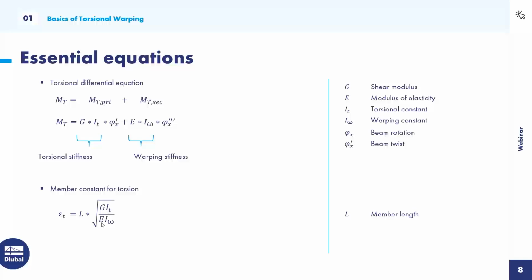And this decay factor has some meaning. The greater the decay factor, the faster the secondary torsional moment is reduced in the vicinity of a warping restraint. We will try to check if this holds in the RFEM calculation within the first practical example later.